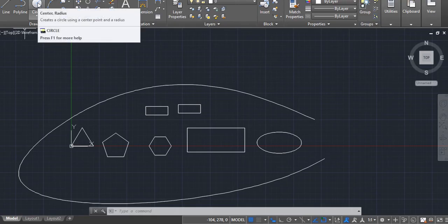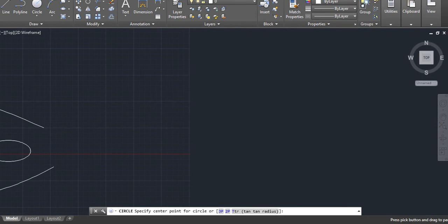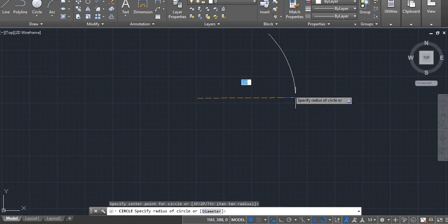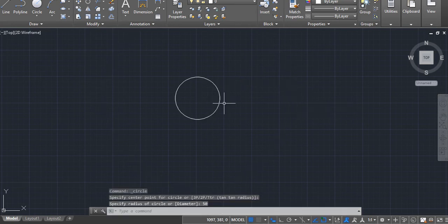Yesterday we talked about ellipse, and I also mentioned the concentric circle method and the rectangular method. Just for illustration purposes, we'll be using AutoCAD to draw an ellipse using the concentric circle method. Let's see how it goes. For this, I want to start out by drawing two circles representing the major and minor diameter of the ellipse. So the major diameter of the ellipse is 100. If the major is 100, that means the radius is 50. Major diameter is 100, so radius will be 50.